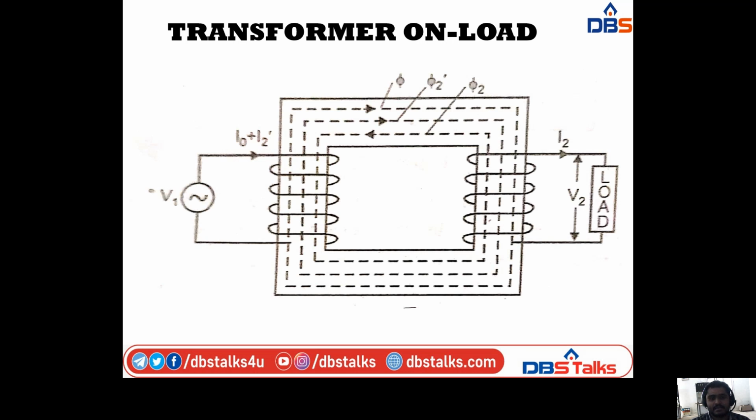So this is the diagram I am taking. Here we have the additional flux, that is phi2 dash, and the additional current, that is I2 dash. Because of this I2 dash, we have the phi2 dash. So phi and phi2 dash are in the same direction and phi2 is in the opposite direction. That means phi2 and phi2 dash cancel each other. This is the I2 dash current and phi2 dash flux, additionally shown in this diagram.